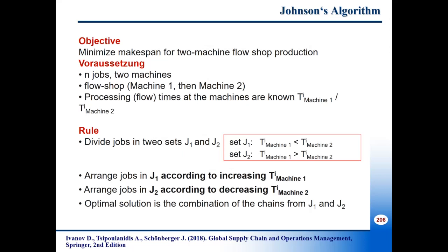An approach to solve the previous slide's scheduling problem is by using Johnson's algorithm. This algorithm follows the principle to keep the idle times of the second machine as short as possible. This is achieved by starting first on the first machine those jobs with the shortest processing time Ti', which can be on machine 1 or machine 2. These jobs are quickly processed by the first machine and then forwarded to the second machine in order to avoid idle times on the last-mentioned machine.